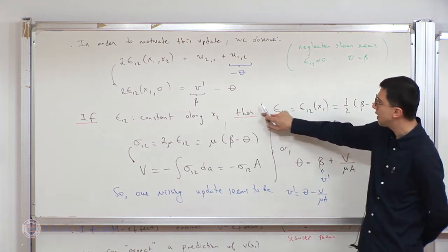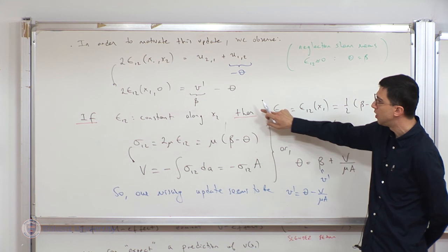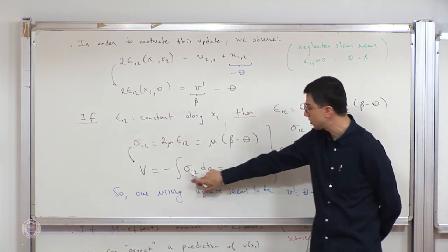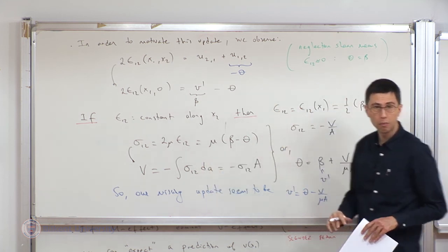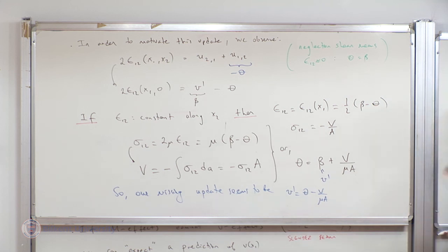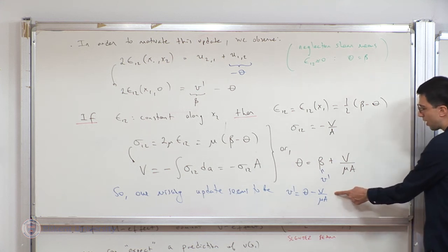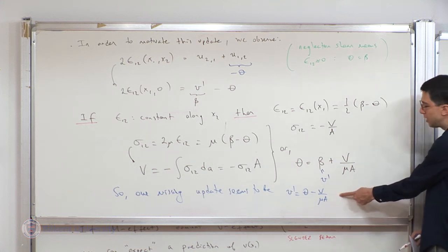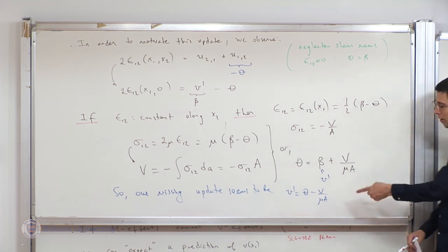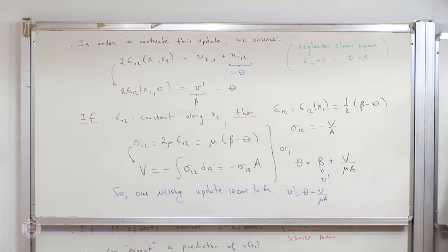No, because I made a very ideal statement that the shear strain and therefore the shear stress is constant along the cross section. Okay, so that's the second layer of approximation on top of plane sections remaining plane. So I am violating two things now, and therefore, even with this update, yes, I do expect, I hope, some improvement over the Euler-Bernoulli beam theory, but this Timoshenko beam theory still will not give an excellent prediction.